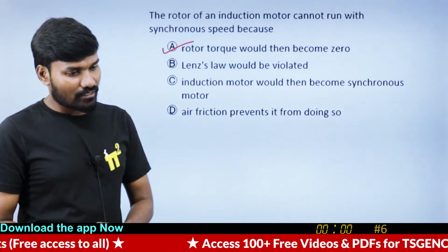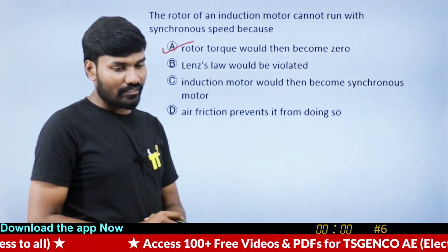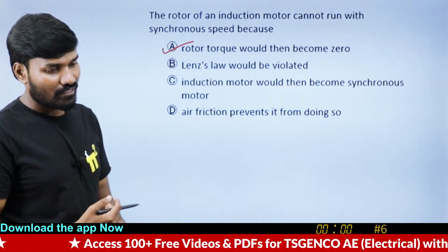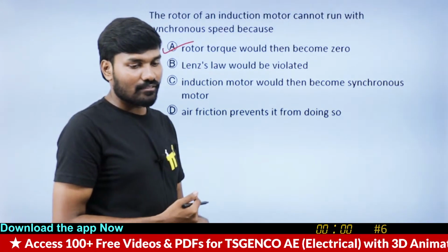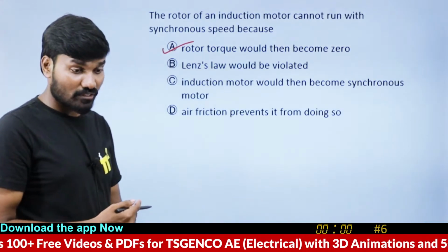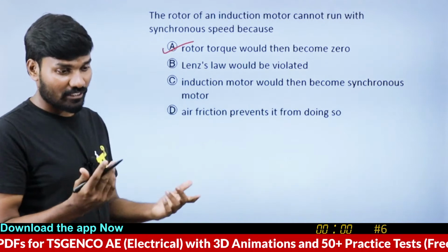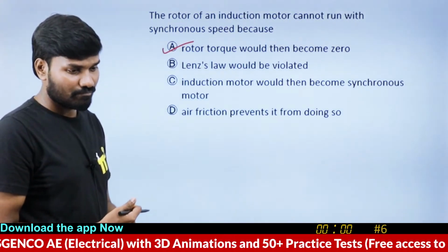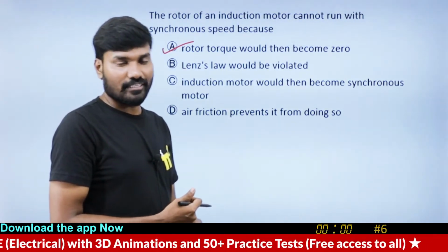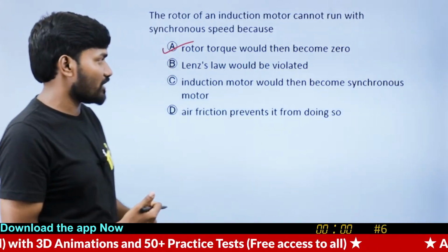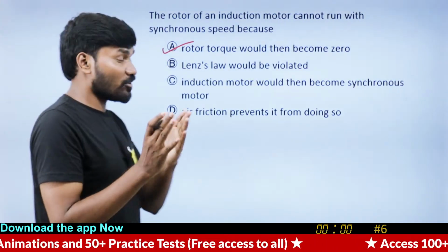I'm talking about SRIM excited from the rotor side. That's what a double fed induction machine is. SRIM excited by the rotor side, and stator is short circuited. That's what you're calling an inverted induction motor. So there, yes, it will rotate in the opposite direction. But that's one of the interview questions.